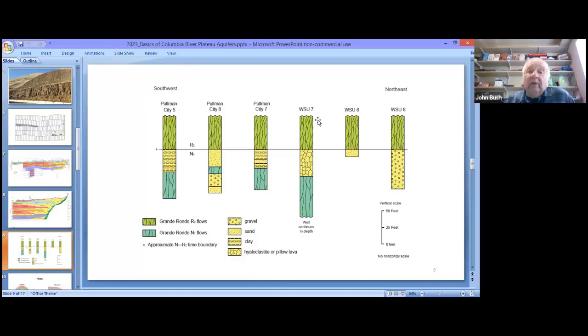Yes, they got water coming down out of some intraflow zones, but I contend the most prolific zone is where they stopped the well, where they had the most water coming in. One of the reasons we don't actually understand how much from each zone is occurring, it's very expensive to stop and run a pump test every time you hit an intraflow zone and determine how much water is coming in. You generally wait till your system's overwhelmed, your hammer tool is flooded, you're looking at the water coming out of the well, and you've now added up to 2,000 or 3,000 gallons a minute, and you stop.